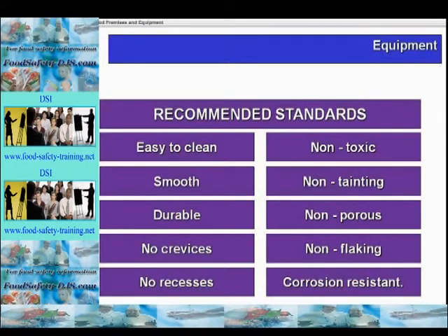They should be easy to clean, smooth, movable to facilitate cleaning, durable, long-lasting, lacking crevices, ridges, projections and sharp edges, and no recesses where food and other debris could accumulate, non-toxic, non-tainting, non-porous or impervious, non-flaking, corrosion resistant, suitable for the intended use and regularly maintained.